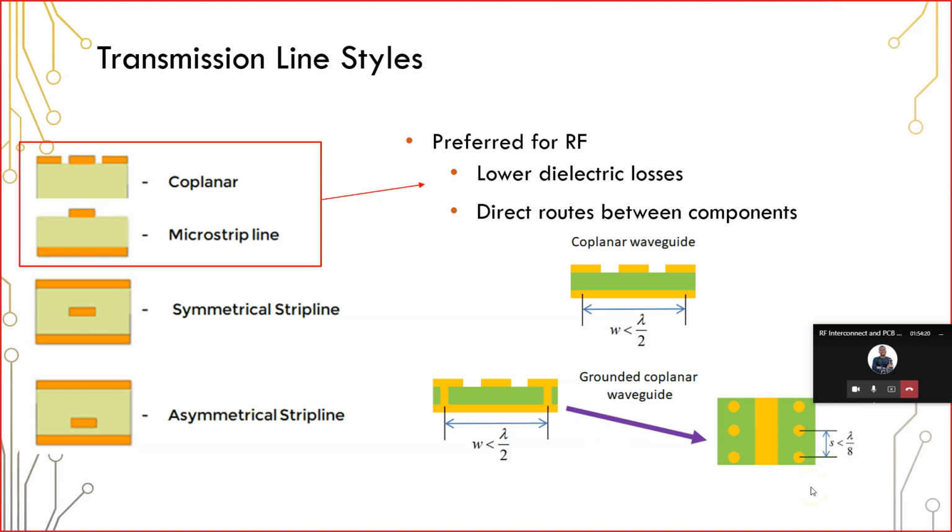However, you have the same problem with what happens at much higher frequencies. Eventually, the frequency gets so high that the distance between these drill centers becomes so small that you can't manufacture it with standard processes. At that point, you then need to either use an alternative process like HDI, where maybe you can get those vias packed closer, and we'll see an example of that in just a little bit.